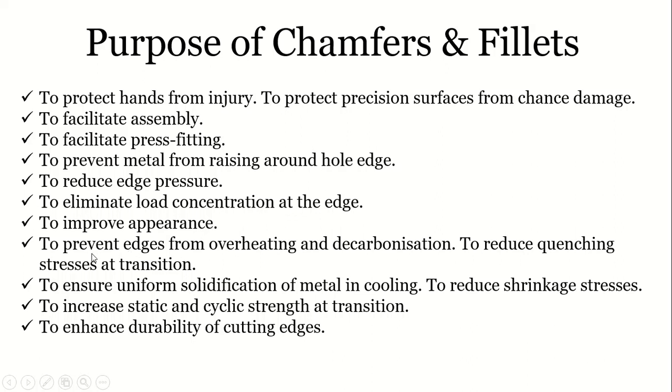And the next item is related to heat treatment. Chamfers and fillets are used to prevent edges from overheating and decarburizing, and they also reduce the quenching stresses at transitions. Another point is related to casting: chamfers and fillets ensure uniform solidification of metal and cooling, and they also reduce the shrinkage stresses.